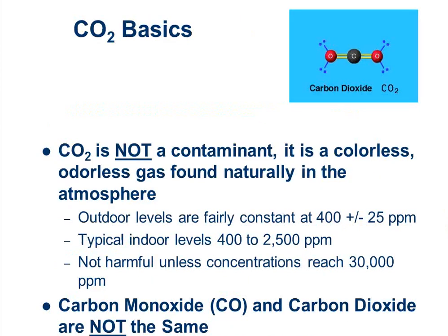So CO2, like I just said, is not a contaminant. It is not harmful to you in normal concentrations. You basically would have to suck it out of a can in order to have it hurt your body, right? You'd have to be up at like 20,000, 30,000 parts per million for it to do any harm to you. And that's basically more because you're lacking oxygen intake, not because of the CO2 itself.